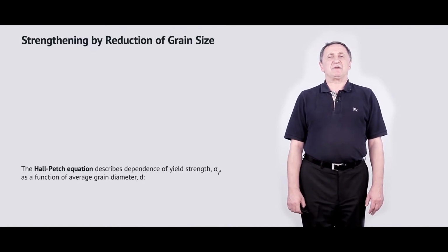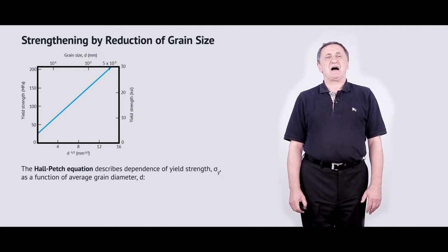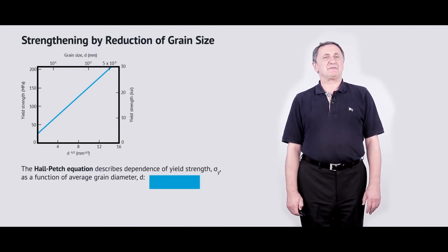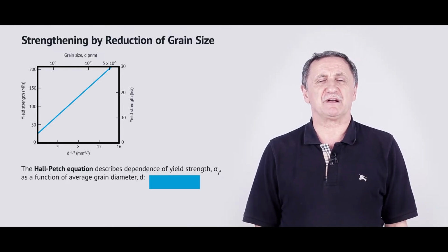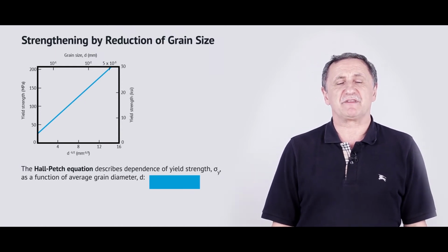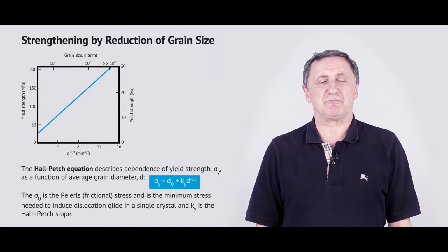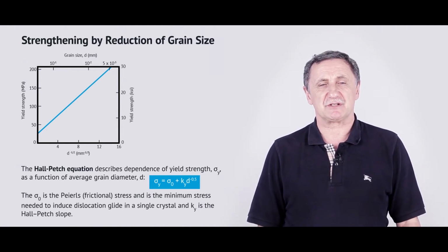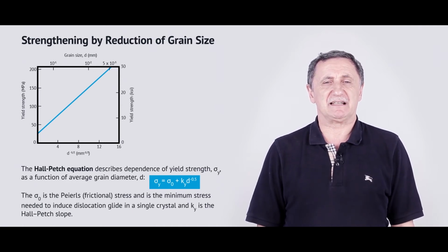On the other hand, please also pay attention that this type of dependence does not work for nanomaterials. It's a separate story to discuss how the mechanical properties of nanomaterials depend on their size. But for an extremely wide range of materials, metals and alloys, where the main mechanism of material failure is due to the slip of different types of dislocations, this formula describes the dependence pretty nicely.